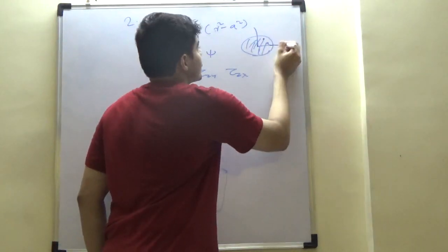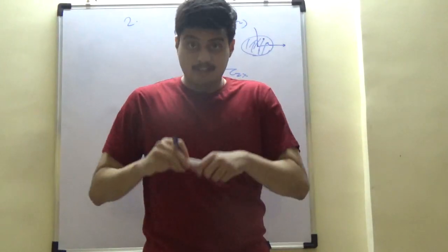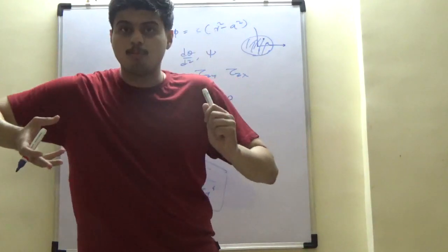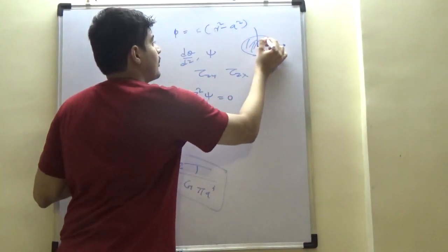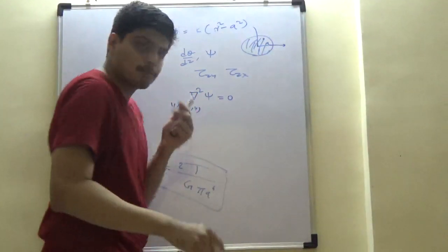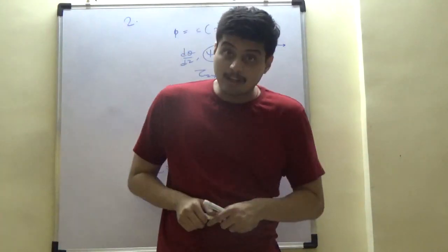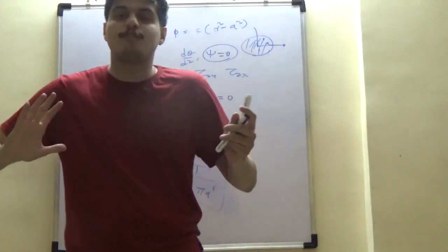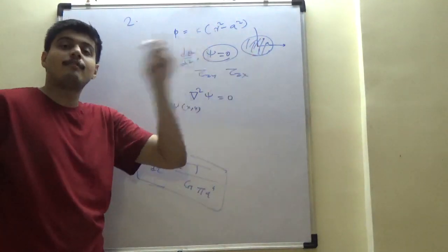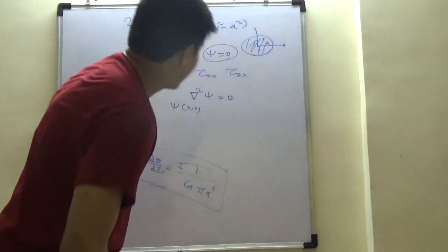But then just by reversing the frame of reference, I would get a different torque. See this induction argument which I am doing. For a solid cross section, when this disk is going to move, if I just shift my coordinate frame, w would change. But circle is doubly symmetric, so just by changing frame it should not change, which means psi has to be 0 everywhere. Circular cross sections of solid nature have no warping, they have pure twist. The rods have no warping but pure twist, and that is an extremely important answer.